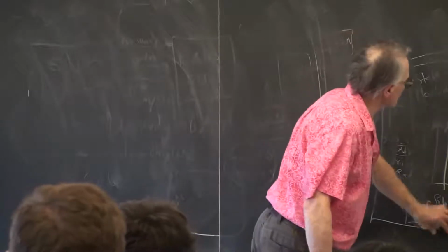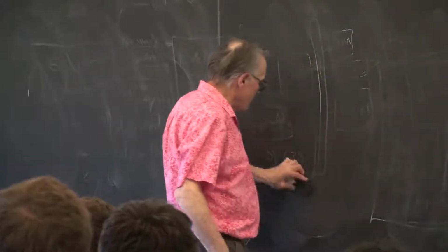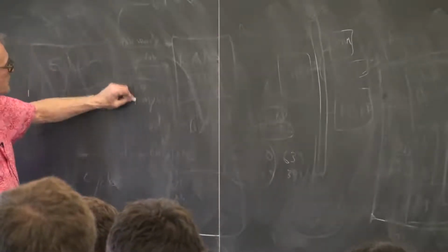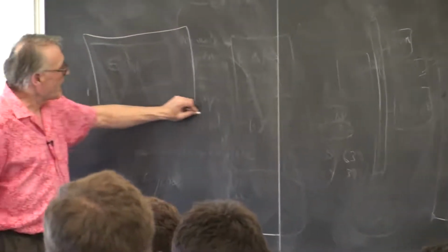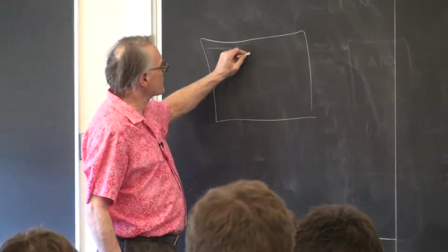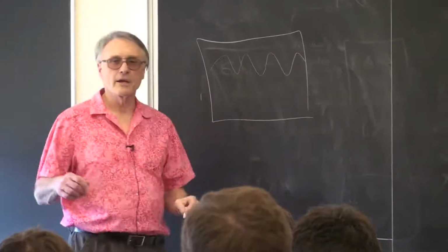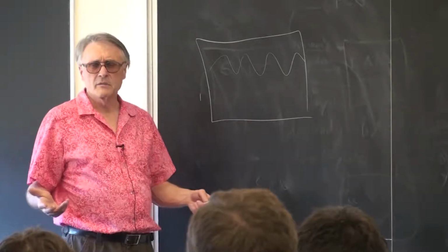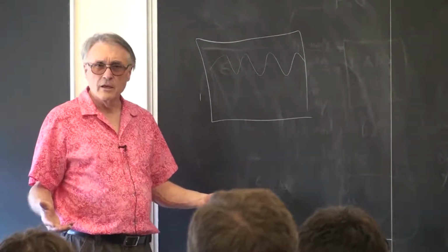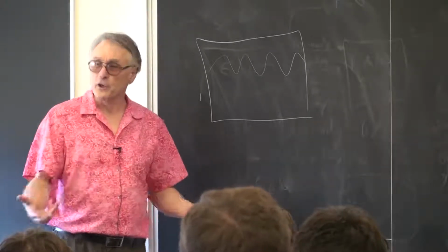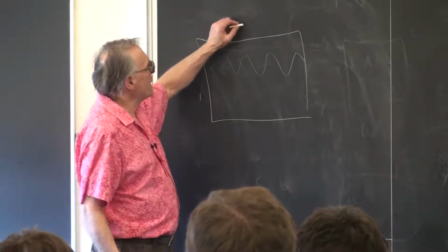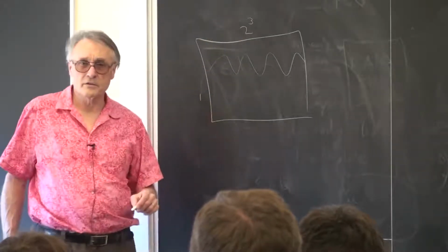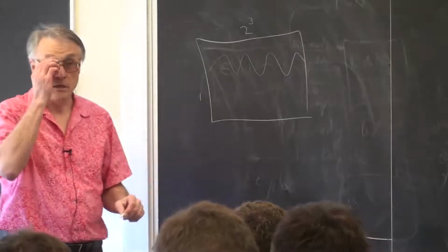So, what I said was I want a few cycles across the screen. So if we look at the VGA, after you've cleared the screen and drawn a screen full, there should be a few cycles, whatever few means. To me that means something like 6 or 7 or 8 or 10, but not 1 and not 30. So let's call this 2 to the 3rd cycles across the screen, 8 cycles across the screen.